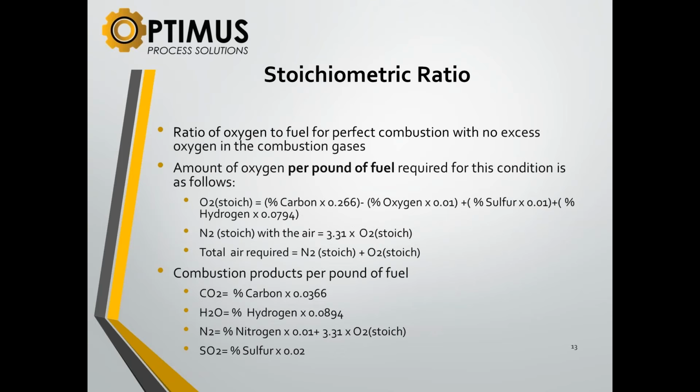So stoichiometric, now we've got a ratio. This big word, stoichiometric. Okay. Well. Sounds German. Yeah, it does. Well, I don't know what that all means, but essentially what it does mean is, in a perfect world, if you added the exact amount of oxygen per our equations that we just went over to burn all the hydrocarbons and not have any oxygen in the gases when you were done, that's what stoichiometric means.